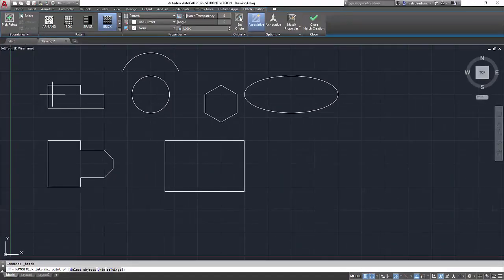Now if I go to this one, you'll see that the hatch will immediately appear in there. If I click it, it will drop it straight inside of that shape. It will drop it in that one, etc. Okay, it won't drop it in anything that's open. So if you've got something that's not completely joined, or something like a single feature, you cannot put hatch in between, like, the circle and this eyebrow. It won't go because it's got an open end. That's the only time you won't be able to put the hatch down.